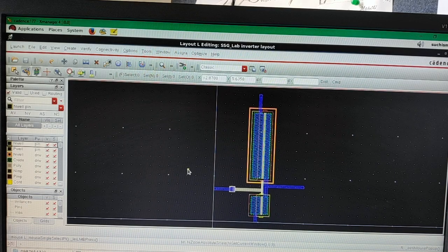The design has to be sent to the foundry people, wherein they will fabricate your design. Now when you're sending the design to your foundry, you're not going to send the schematic or the test circuit. That is of no use to them. They don't bother themselves with that. What they want is the GDSII format that is generated from the layout, nothing else than that. Since the GDSII format required to fabricate your ICs is generated from the layout, hence your layout should match the schematic.